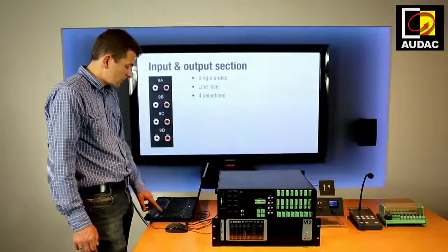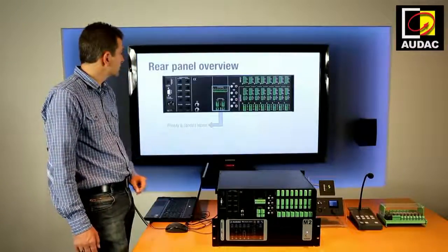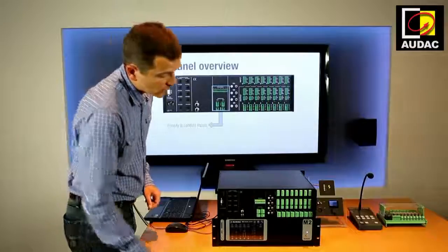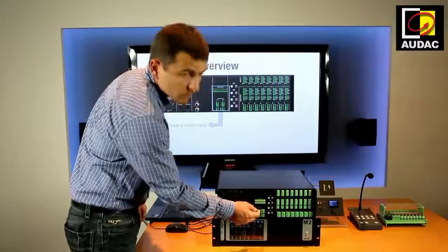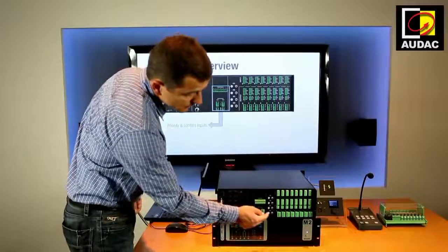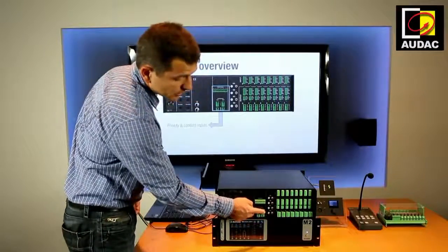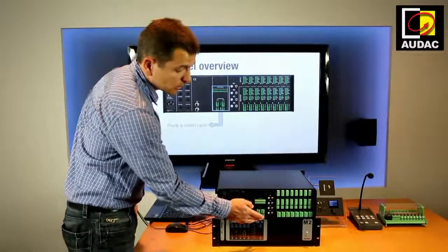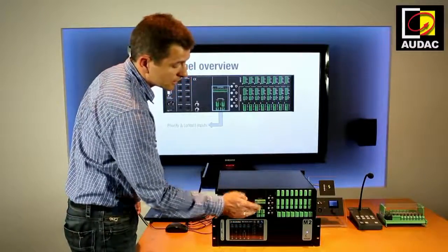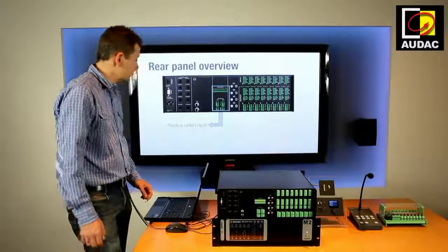If you take a closer look, okay, I told this already. And the priority inputs, priority input 1, mono balanced, galvanic isolation. Number 2 the same. 2 priority contact inputs. These are multi-purpose, and 8 extra contact inputs also multi-purpose.